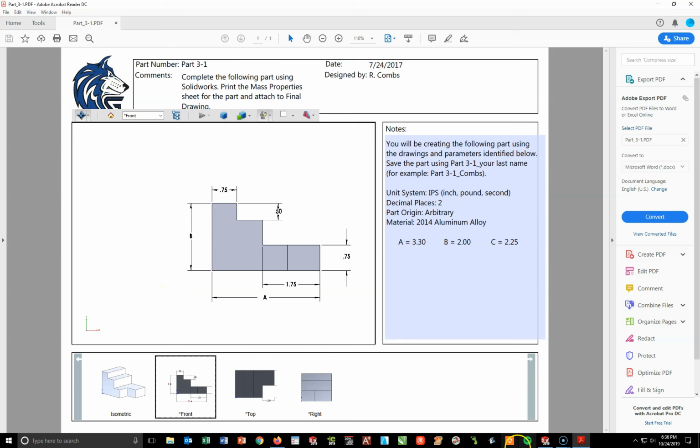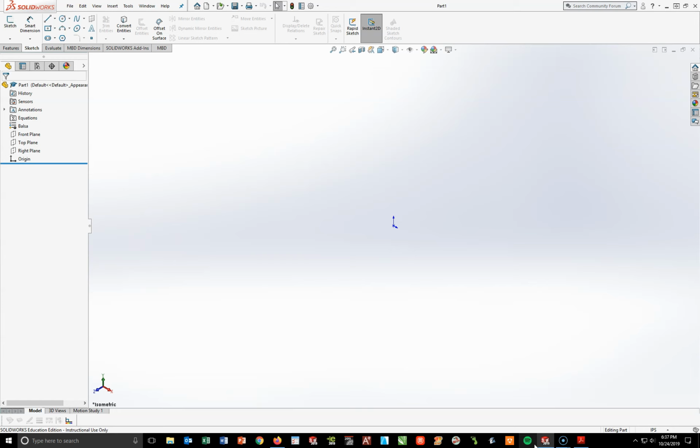So when I go back into my SOLIDWORKS here, I'm going to start a drawing or a sketch on a front plane. Now, to do the front plane, if you look over here to your left, where I'm circling around with my cursor, what you see here is what's called a design tree. You're going to hear that very frequently, me reference it. You always want to look to your design tree, and as we begin designing our parts, you're going to notice that your design tree will start adding things to it. Each thing it adds is called a branch. So by the time we're done with a part, we'll see several branches over here that we can go back and look at and manipulate.